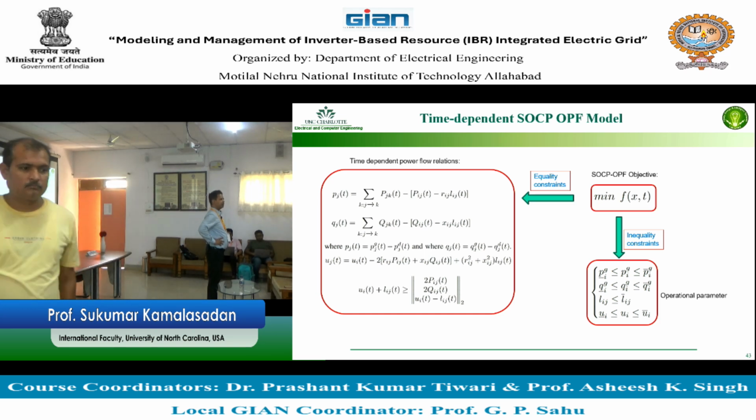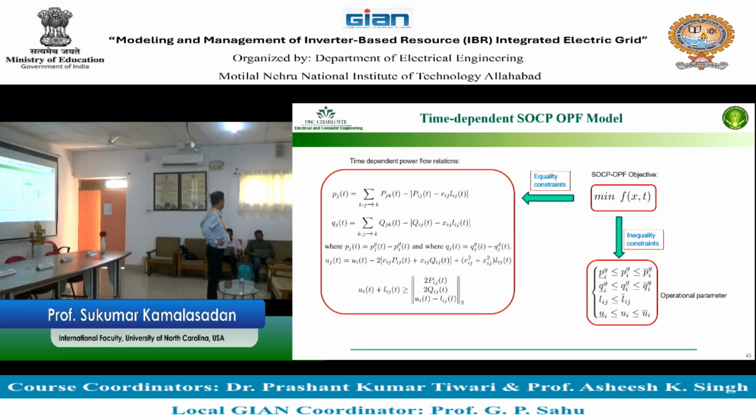Can you tell me an equation for active power in AC in terms of voltage? P is equal to VI cos theta. For a power flow, what is the equation for active power? Same equation? No, it's not the same equation. Injected power is equal to, so with two buses, what is the power flowing between bus number 1 and 2? P12. Understand what you mean by P12. What is the equation?